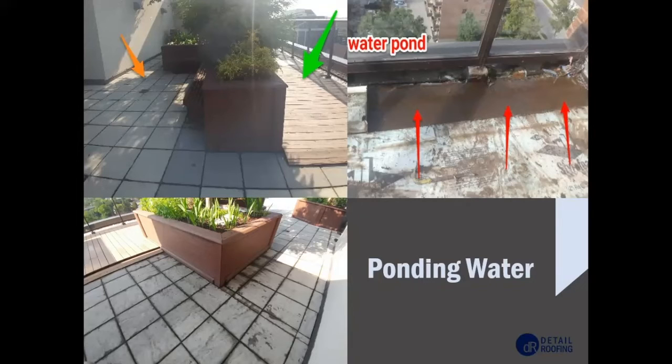The photo below does show some of the water coming up where the drain is, coming up through between the paving stones. So in this case, there wasn't a clear path for the water to be traveling below the inverted roof system when there was heavy rainfall.